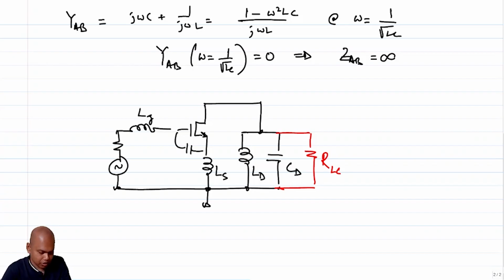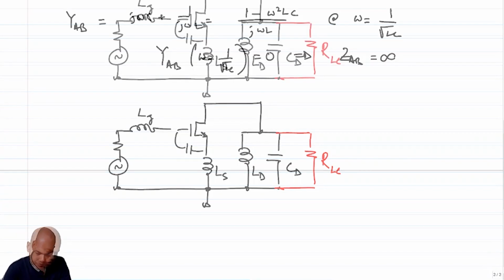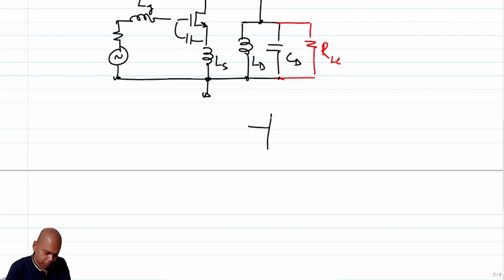Okay. So now the question is, what happens to this? You will not be ultimately using this LNA in isolation, right? The LNA is going to feed the next stage, and what is typically the next stage of the LNA? That is generally a mixer, right? So now, let me simply draw the LNA as a voltage controlled voltage source and a resistance, and you have a mixer which is operating at FLO.